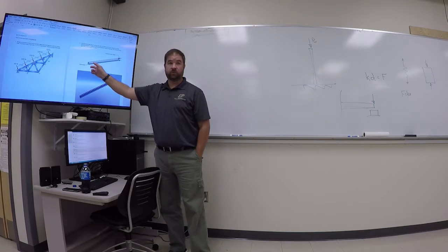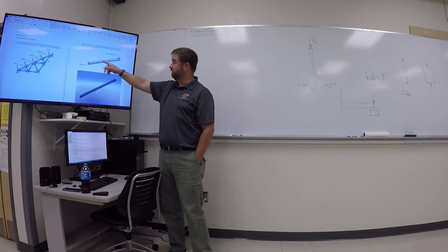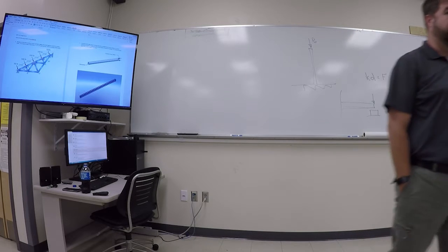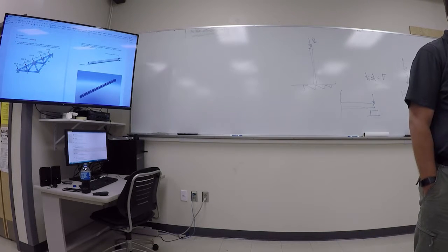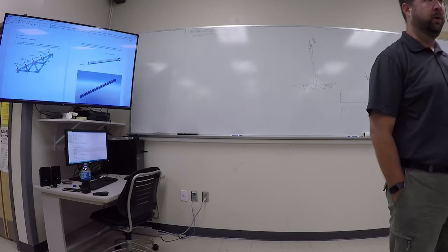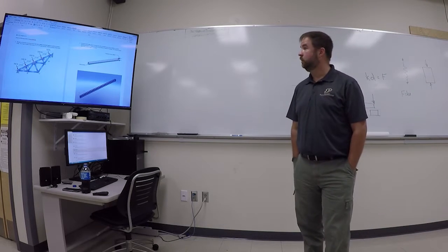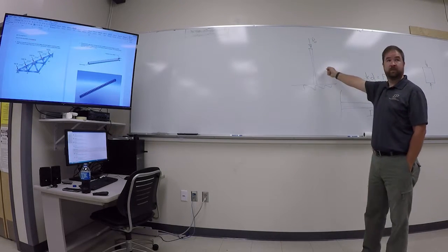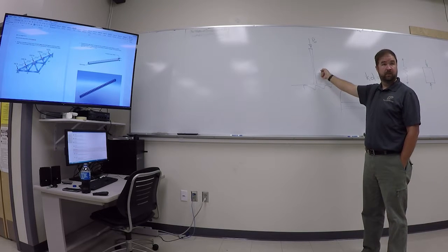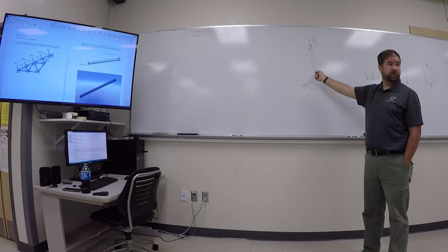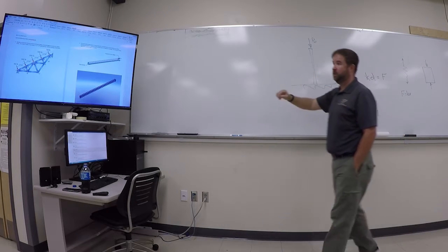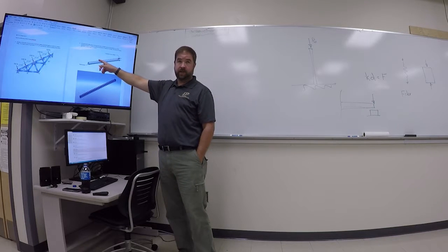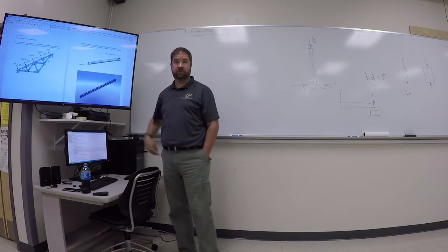This is more like what we did in 211. The difference here is that this, because it has the holes in it, does not have a standard modulus of elasticity or a moment of inertia, right? The moment of inertia is smaller where the holes are than where the holes aren't. So can we calculate this using 211 strength of materials equations? Yeah, we can approximate it. We could probably get an upper and lower bounds on the P critical. You use the smallest cross section to calculate the P critical, and use the largest cross section to calculate P critical, and our actual P critical should be somewhere in between.